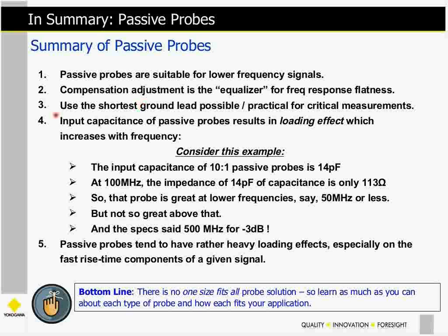We saw about 6 slides of how easy it is, even at low frequencies, to have a probe ring due to the LC circuit that is part of its makeup. And the issue there is the fast rise time of your waveform. The input capacitance results in a loading effect.